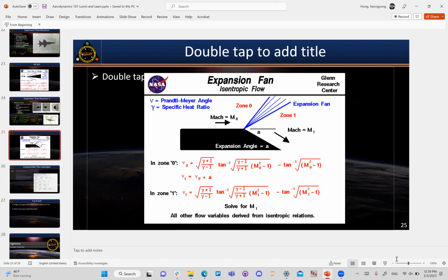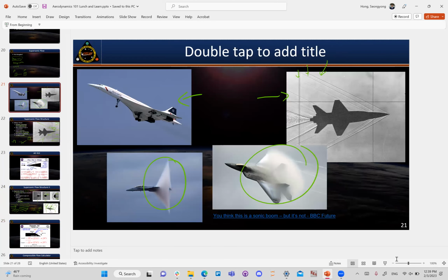Okay. And going back to the vapor cone example. This is water vapor in the air dropping out because the pressure is dropping because the temperature is dropping. What drops temperature and pressure? Is it compression shock waves or is it expansion waves? Expansion. Yes, expansion waves. So what you see here is not a shock wave, for crying out loud.